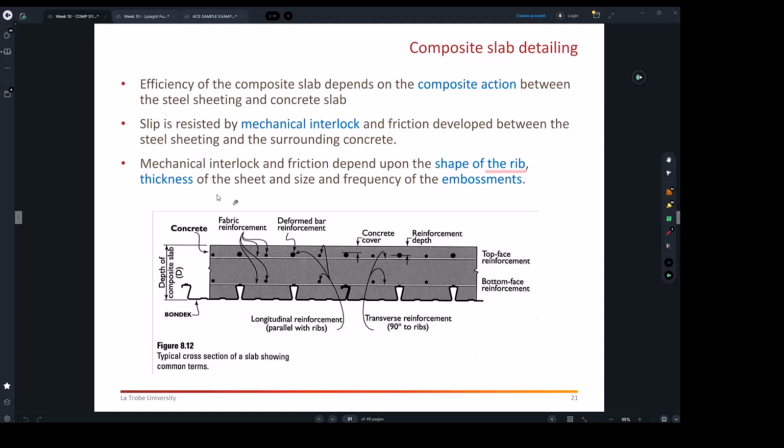So as a practicing construction engineer, as I said, you won't really be calculating these things from theory. You will just need to use the span tables, which I shared with you. But you need to understand you can't make a decision on changing the profiles from one to another, because that will change the capacity and you're going to be changing the theory. You have to go back to the engineers.